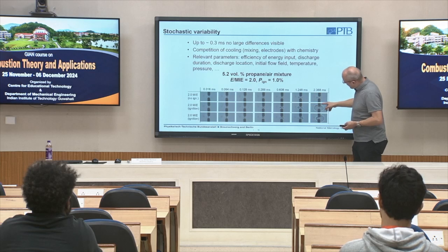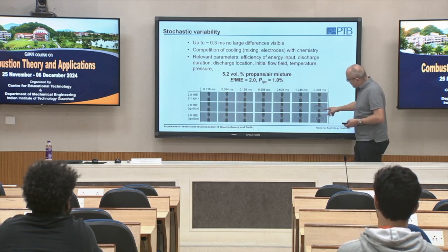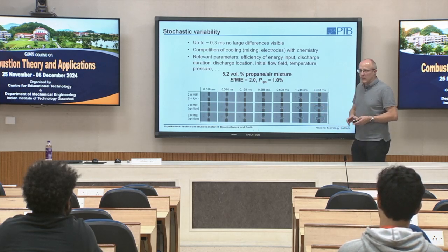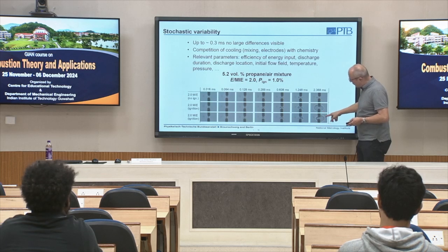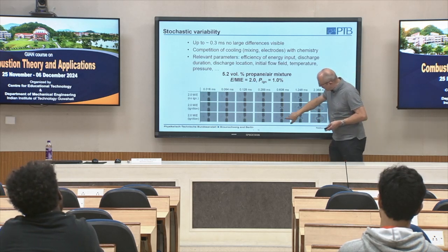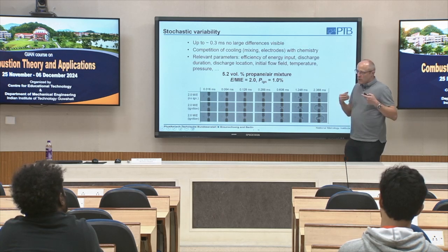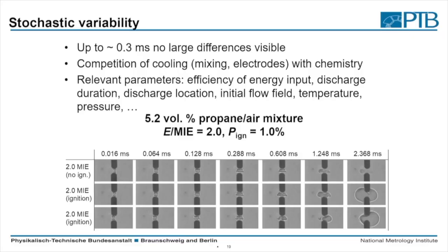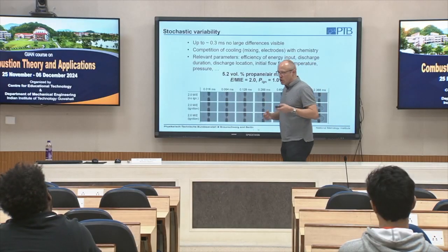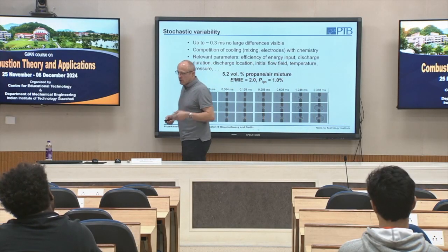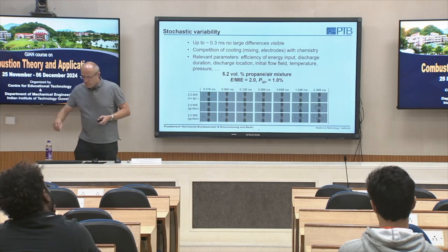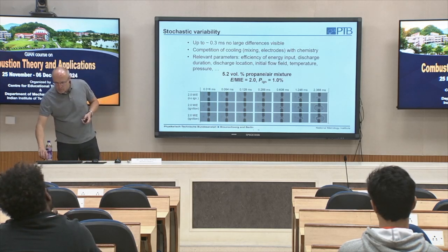But of course it can happen that there is a clear spherical flame propagation, but also this is visible, that the ignition has taken place here on the right side. So we do not have to focus only on the energy and the volume of the plasma. Here, of course, we have to consider the subsequent fluid interaction of the surrounding with our hot gas kernel.